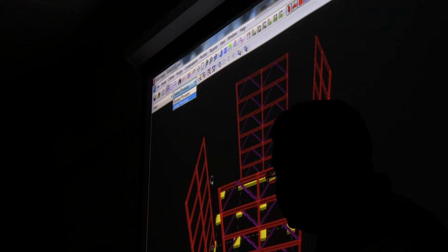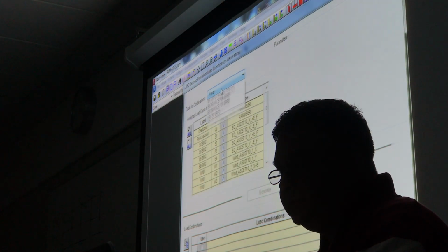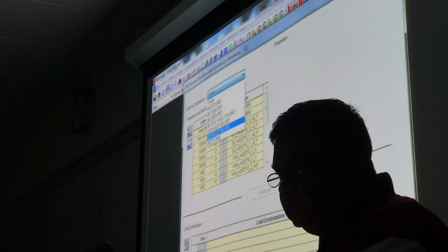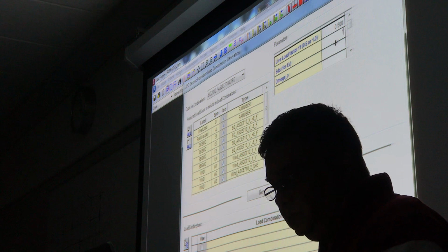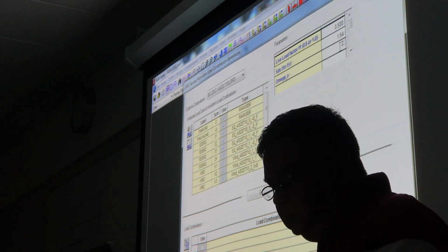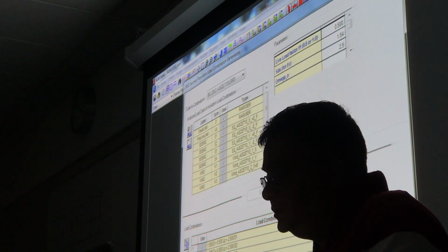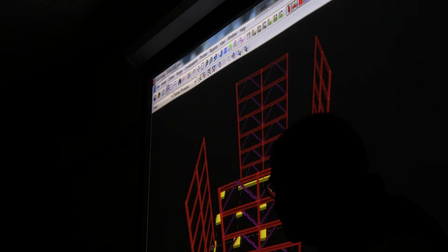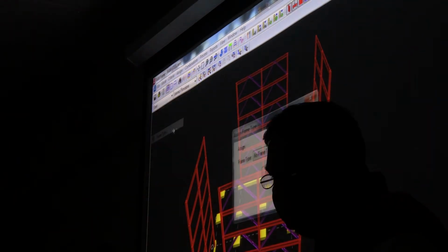Another provision is called seismic provision, that you have to do it later. Okay. And that comes from, there is an omega factor, which is called overstrength factor. Again, these are all part of the code. Okay. Now also you have to assign frame type.